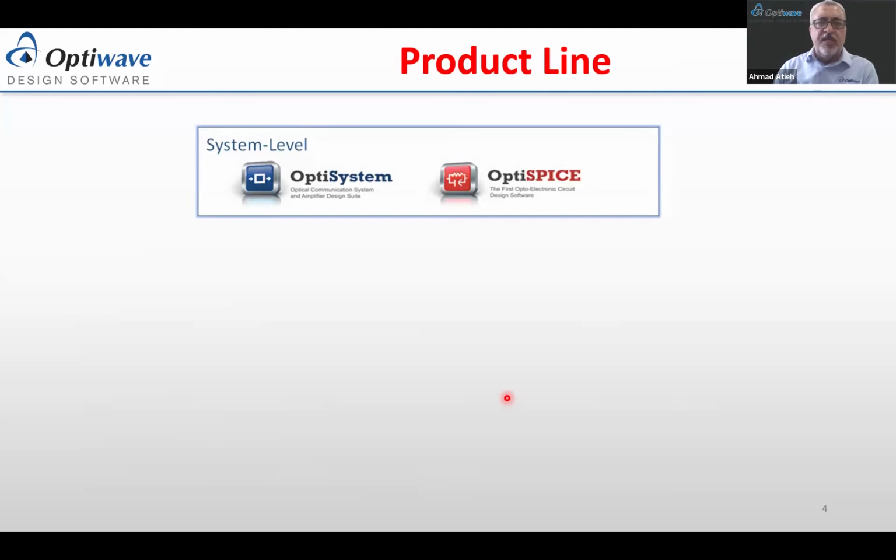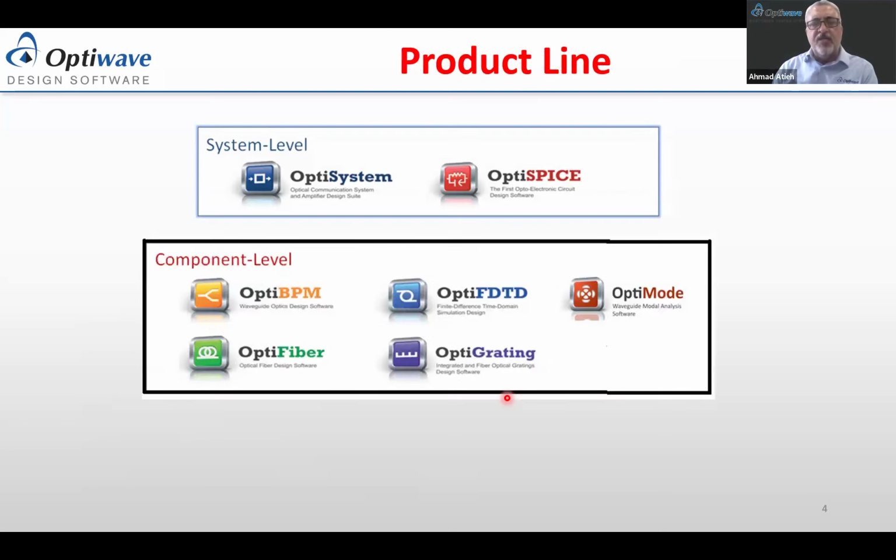You can design optoelectronic circuits in the same layout and do simulation. The other software packages are at the component level, including finite difference time domain, which is OptiFDTD, as well as mode solvers, OptiMode, and beam propagation method, OptiBPM, and then 2 other software used for designing different types of fibers, single mode, multi-mode, and so on, as well as grating design, which you can design fiber Bragg gratings, short period, long period gratings, tilted gratings as well.